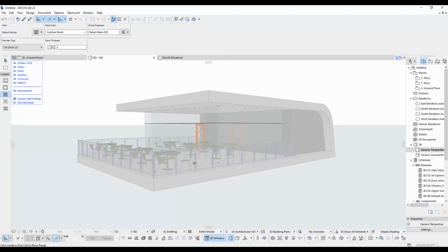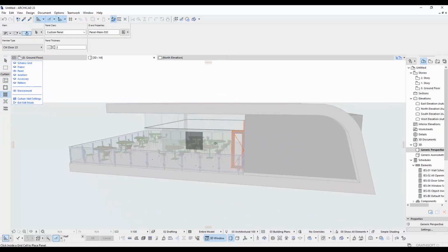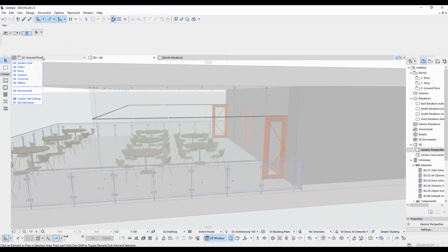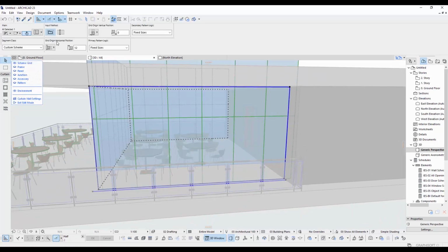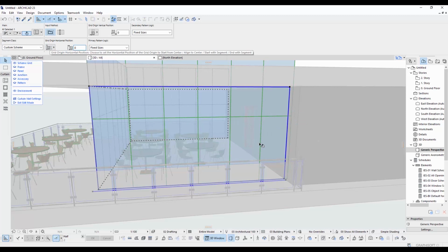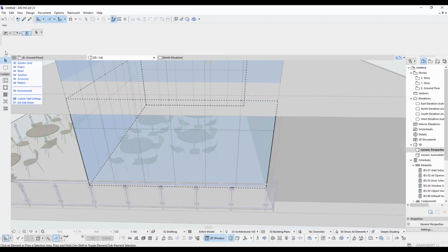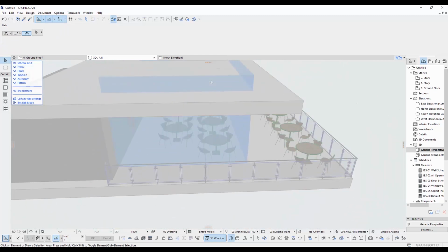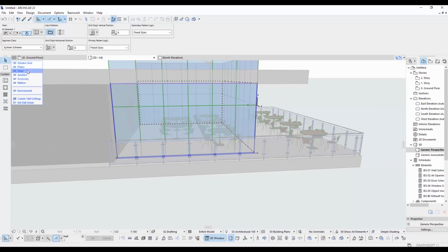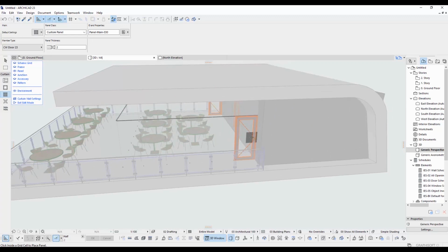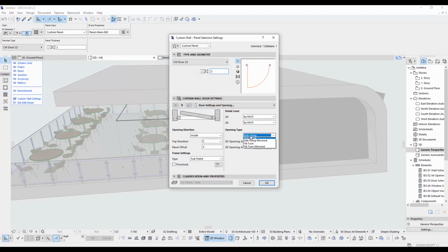I'm just gonna open a door here too, but that door panel needs to be adjusted, at least 90 cm. So I'm just gonna select the scheme and change the offset value. Or I can just click and drag it manually. I can change the settings of the door with Ctrl+T and I will mirror the door to fix the orientation.